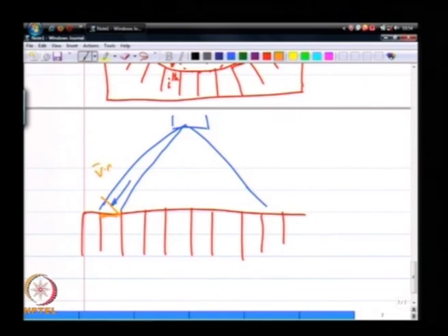They measure volume flux. So, let us make sure we get the units right on this. Say I run one of these for a minute, and in that minute I collect so many cc of fuel or liquid. If I divide this by the area and then by the time I have taken to collect the liquid, this forms the units of measurement.